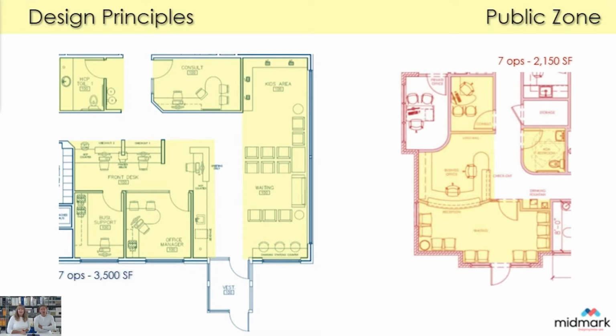So what we would say about organizing a waiting area in the public zone is that you want to have all the seating segregated off to the right or off to the left, where you don't feel like you're walking through and interrupting that flow. That feels better to people who are entering the space. Also notice the seating distance between the image on the left, if I'm seated in a waiting area, to the front desk, versus the one on the right. On the right, you've got a chair that's within 2 feet of that front desk area. That's really tight. That's very close. That's not comfortable. Another significant difference between these two is the orientation and the receiving desk area of the reappointing.